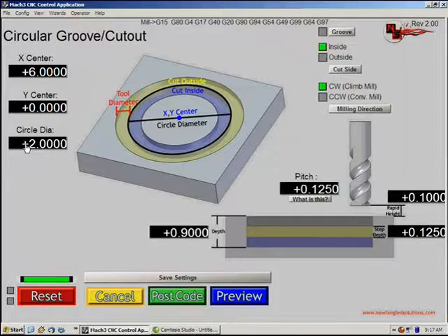That's fine. And we're going to cut a 2-inch diameter pocket. Now, this groove command stops your entry moves from happening inside the part. So if I actually wanted to cut this groove right here, I could use this groove command. It would do its compensation move above, drop down, and then cut the part. So I could have an oil ring groove or anything like that if I was building a small steam engine, or just needed a circle to be cut out in a part.